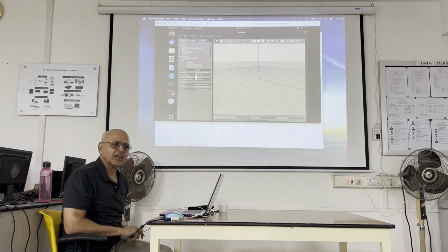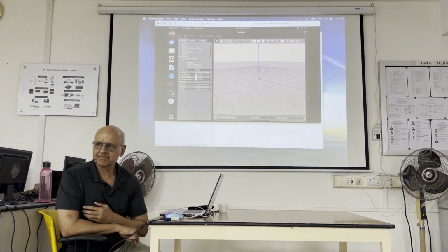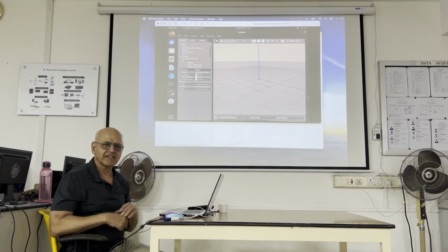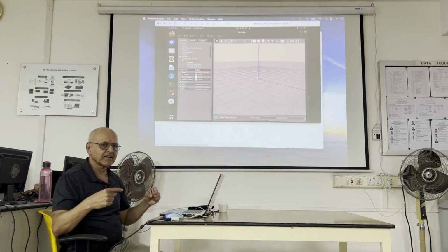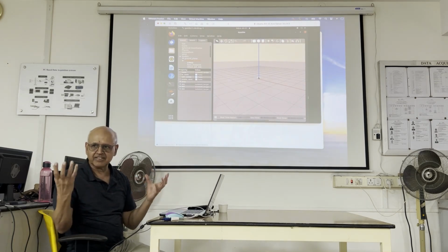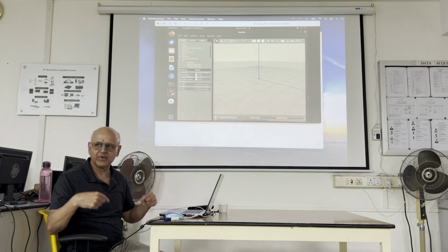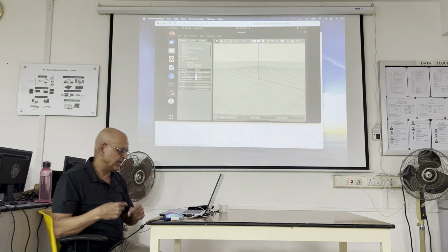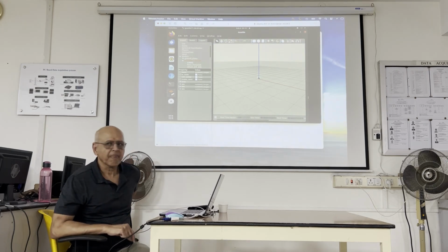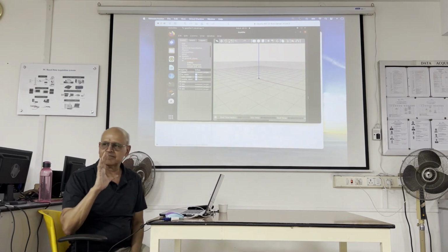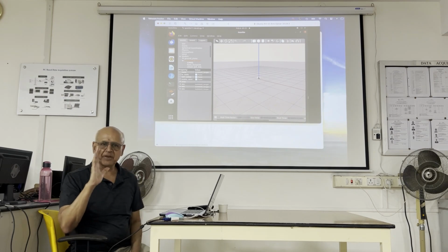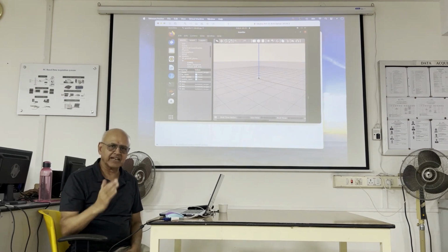So, we're going to learn how to read odometry. So odometry, the odometer, which is a sensor, is counting the fractional rotations of the wheel. Now how does it do that? It's because they have an optical disc with alternate black and white sectors.